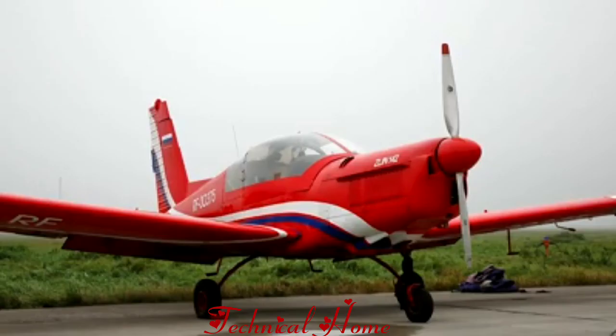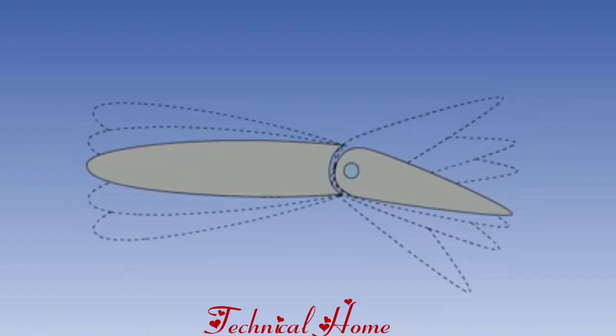There is one more form of balancing that is applicable to flying control surfaces, but this time it has nothing to do with assisting the pilot to operate the controls or to reduce stick force. It is known as mass balancing, and its purpose is to reduce control surface flutter. Flutter is a phenomenon associated with the higher speeds of aircraft. It is an oscillation of the control surface, coupled with an oscillation and bending or twisting of the wing, fin or tailplane. It can occur on aircraft with manual or powered flight controls.